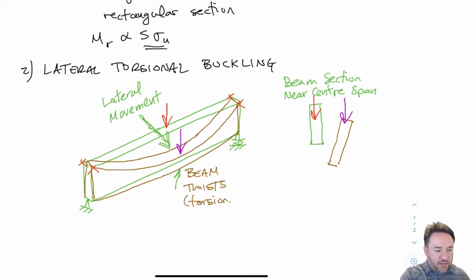And the reason that it buckles is because, as we said, when we bend a beam, the bottom is in tension and the top is in compression. So basically what's happening is, since the top half of this beam is in compression, it can buckle just like a total column in compression can buckle. So we have a buckling phenomenon happening, but just on the top. So the bottom tends to want to stay straight because it is in tension during this process.